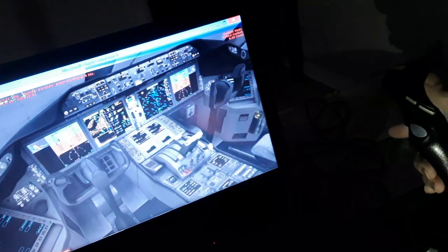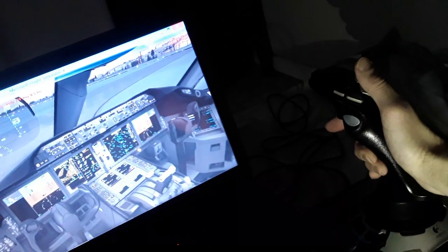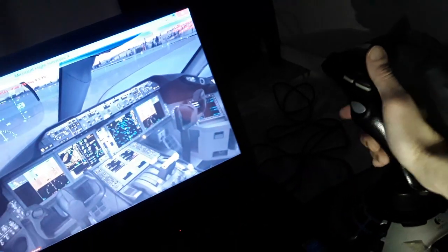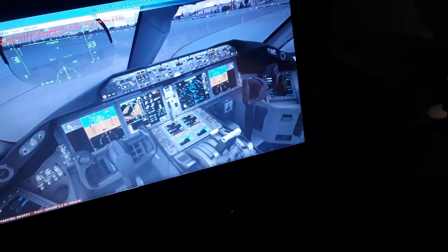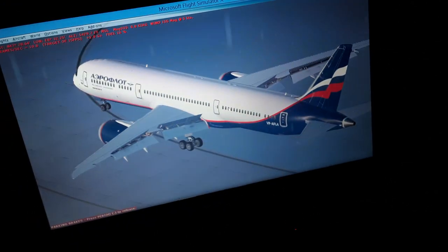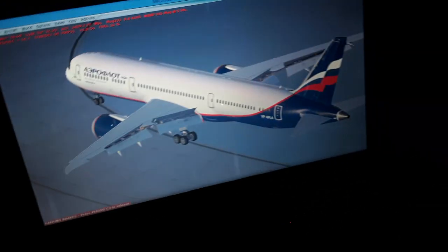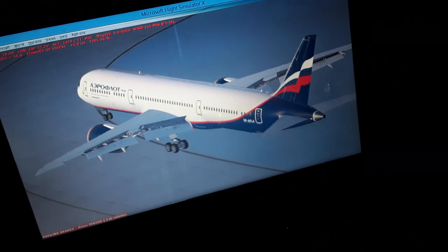We have the vertical stabilizer interconnected for the rudder control, and also the nose wheel steering. So we move the nose wheel 76 degrees from 0 to 45 knots in takeoff. Then it decreases from 76 degrees to 7.6, all the way up to 80 knots.